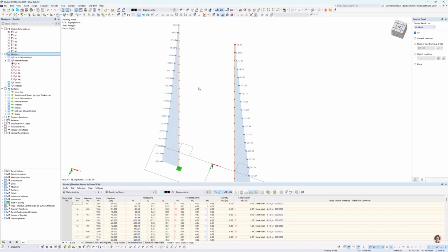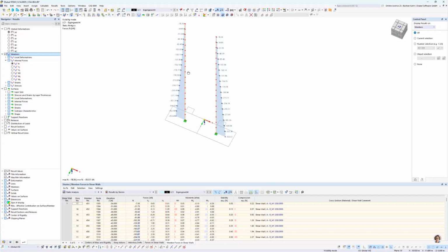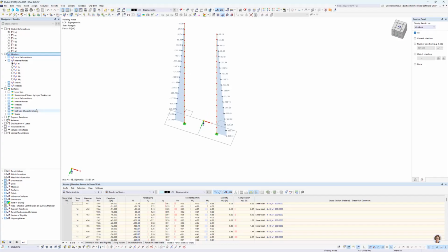But one will say I have quite a high loading of 3.4 kilonewton per square meter. And I don't want to recalculate that now in detail, but I also have a very high self-weight, or a mass in the center of 34 tons. So 18 for the center column probably is too low in here. And why is this occurring?